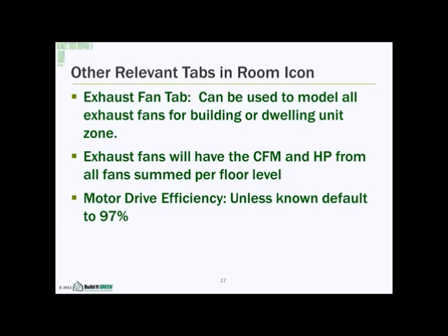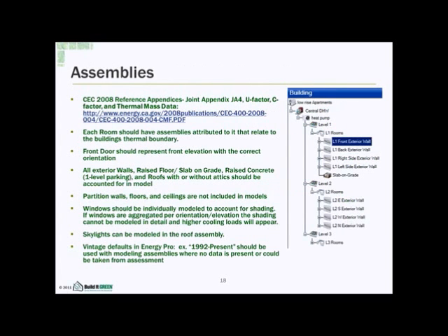So the motor drive efficiency, I think the default is 97%, and unless you pull apart the exhaust fan, you're not going to really know what the motor efficiency is. So I would just default to the 97%.